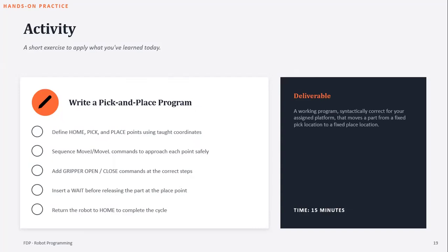Whether you are a student or a teacher, a faculty member from a leading reputed college, your primary duty is to develop a simple robot program for a pick and place operation, identify the required motion commands used, define the sequence of operation, and discuss the possible programming errors and how you are going to recover from those errors with the support of your colleagues. So take this as an exercise. You can do it in your own workplace and try to explore the importance of robot programming.